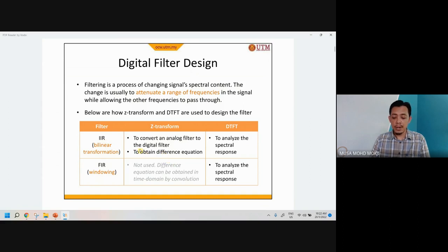Right? So that's the difference. Because for IIR, practically, we cannot do convolution. That's why we try to find the difference equation so that we can solve the difference equation. For FIR, we find Hn, the impulse response, because we can use that impulse response to do convolution. After you have your Hn, the impulse response, you do convolution with your input signal. Because for FIR, practically, we can do convolution. Conceptually and theoretically both are doing convolution, but practically for IIR, we cannot do that.